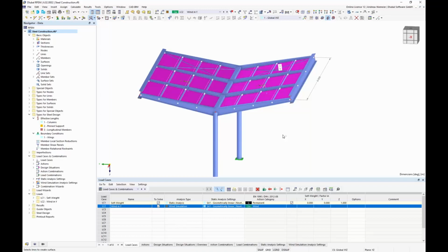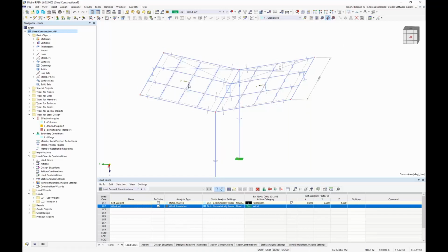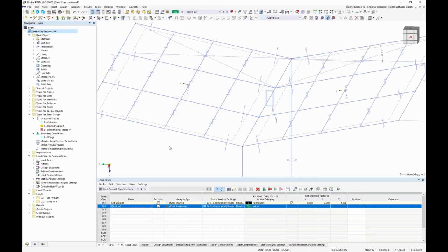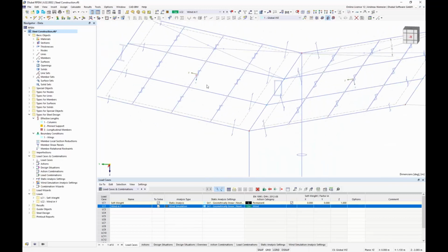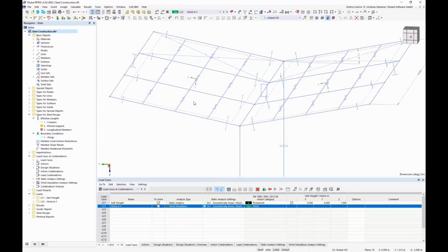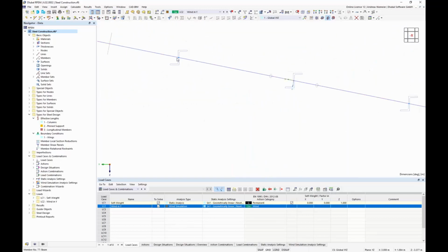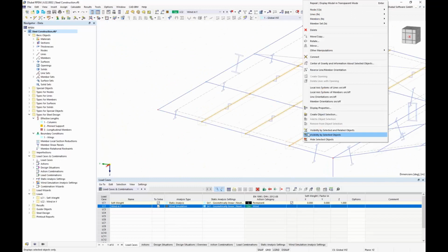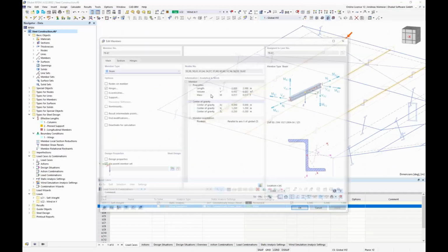But at the moment I said this surface has this property, but I haven't shown you how this is working. So let's take some minutes to explain how this surface itself is working and which features you have. So the first feature of a surface in member structures is that you have here a coordinate system of the surface itself, and this gives us the option to orientate members according to this. So if we check maybe the input, you will see, oh, the author of the file didn't place these members right, but we can select it now and right click, properties of members, edit,